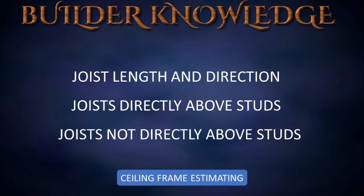Ceiling frame material estimating process. Determine joist length and direction from blueprints. Joists placed directly above studs, 16 inches on center: the number of joists equals 0.75 times the building length plus 1. Joists not placed directly above studs, 24 inches on center: the number of joists equals 0.5 times the building length plus 1.